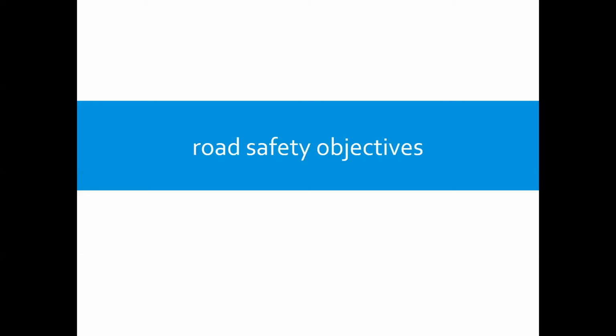The concept of designing a forgiving roadside should not be regarded as a byproduct of the application of safety criteria to each design element, but as an integral part of the total engineering of the major urban road. The need for a forgiving roadside is paramount on the outside of horizontal curves with radii of less than 1,000 meters, which are quite common in urban areas, where the possibility of the errant vehicle running off the road is greatest. However,